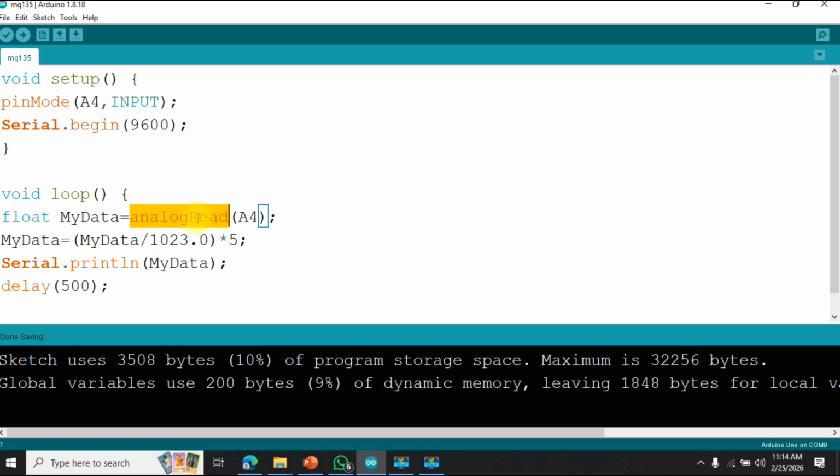From the Arduino UNO to the serial monitor, we need to show the results, so it needs to send the data. Arduino UNO has to send the data to this laptop through the serial cable. So we need to initiate the command Serial.begin, and 9600 is bits per second, so it is a ratio called BPS, the so-called baud rate.